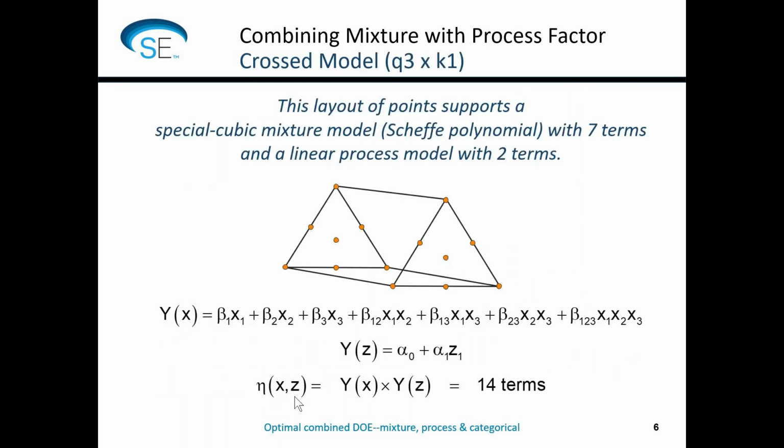All right, now the layout of this particular structure that we're showing here with the overall centroid shown in the mixture space, the binary blends, which are the sides of the edges, and the complete blends, which are the pure blends at the corners. We then have enough data to provide what's called a special cubic mixture model that was invented by Scheffé in the 1950s. And these are specialized models that are different than the typical ones you see for processes.